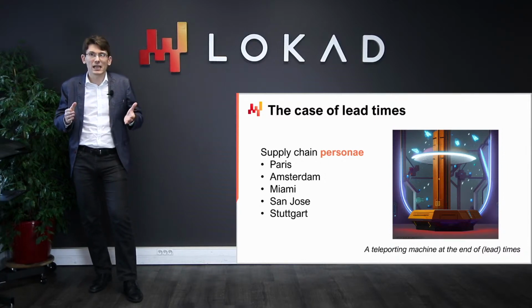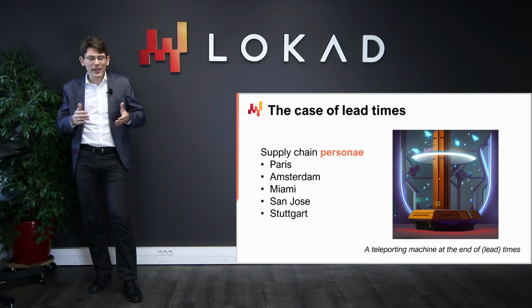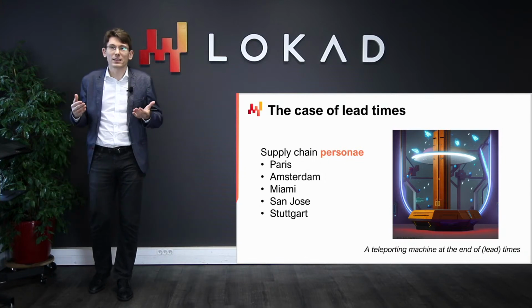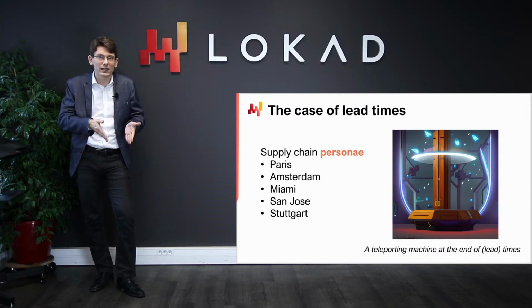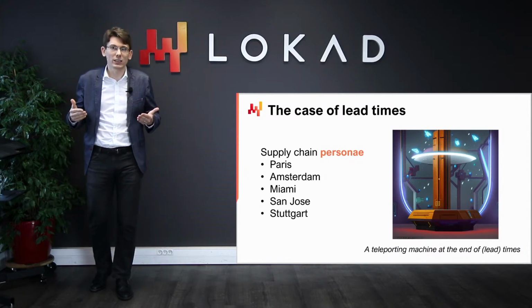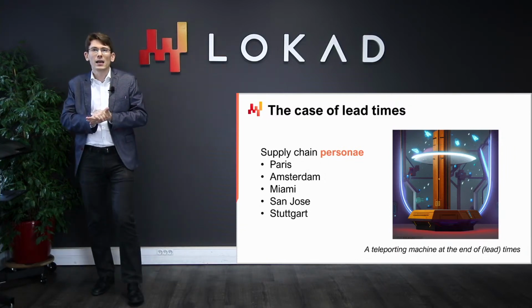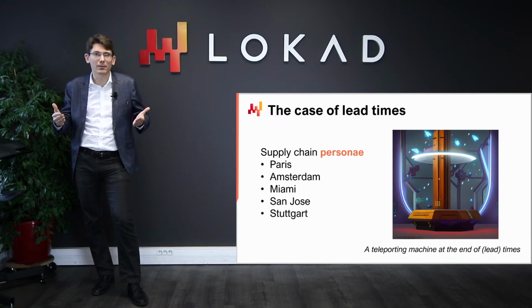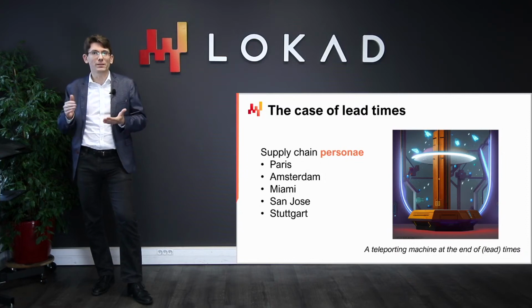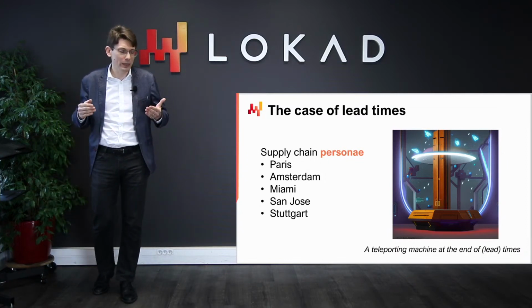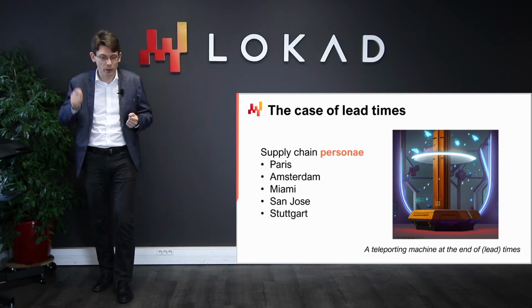Miami is a fictitious aviation MRO. MRO stands for maintenance, repair, and overhaul. Every jetliner needs thousands of parts on a yearly basis to keep flying. A single missing part is likely to ground the aircraft. The repair duration for a repairable part, also referred to as the TAT, the turnaround time, defines when the rotable part becomes serviceable again. Yet the TAT varies from days to months depending on the extent of the repairs, which aren't known at the time the part is removed from the aircraft. Those TATs require a forecast.